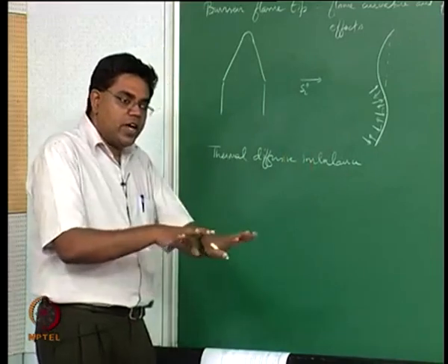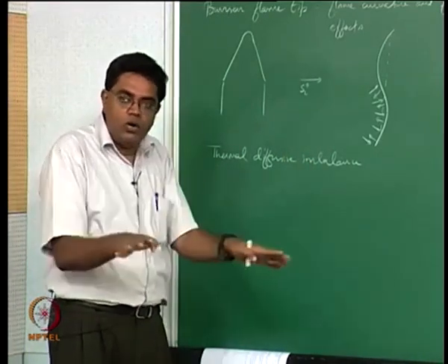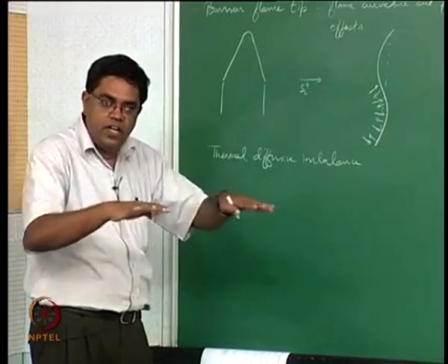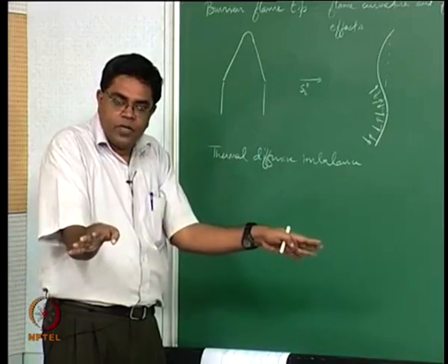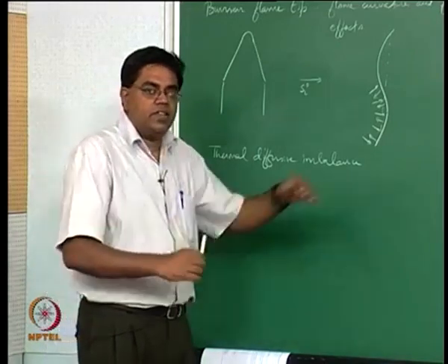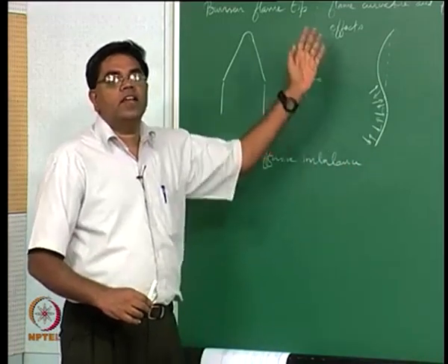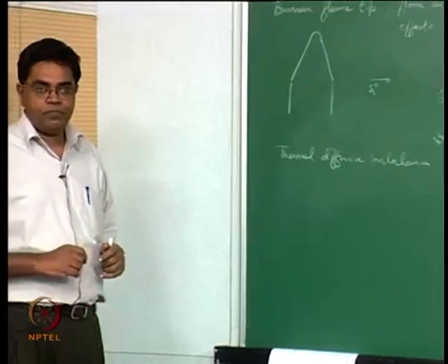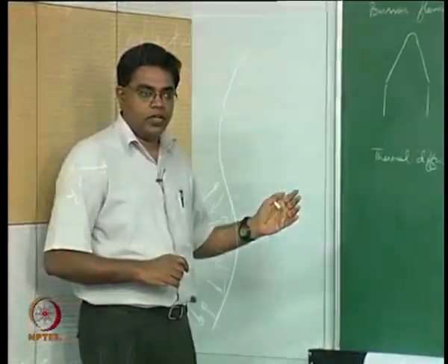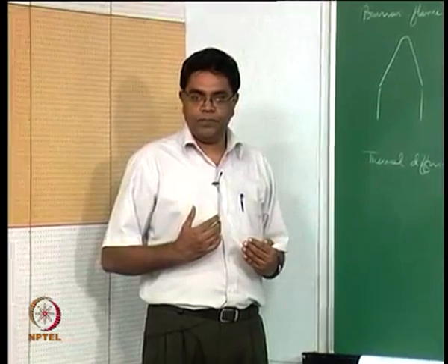The deficient reactant now spreads thinner in a radially outward manner. So instead of feeding a planar flame straight, it is spreading itself thin. That means the flame is running out of the deficient reactant more than in the case of a planar flame, if you have a concave curvature relative to the upstream. So this has a tendency to decrease the flame speed.